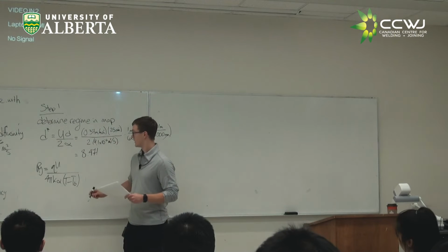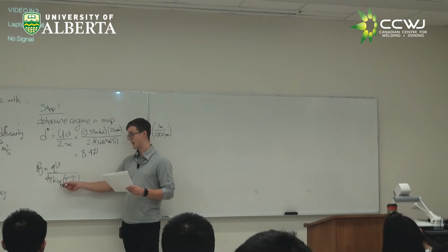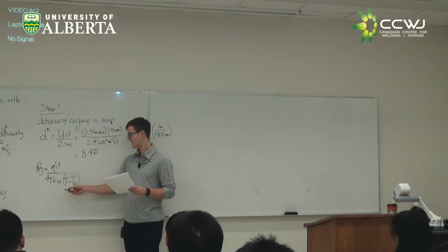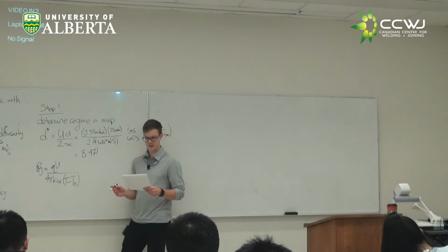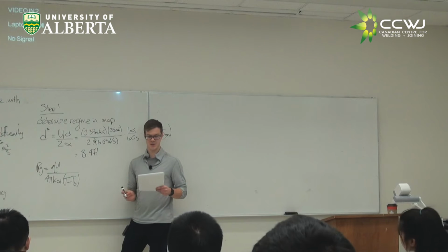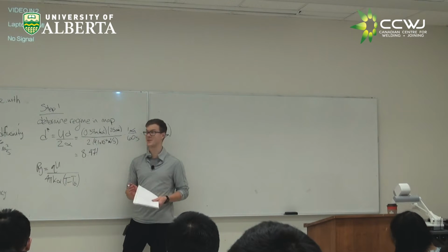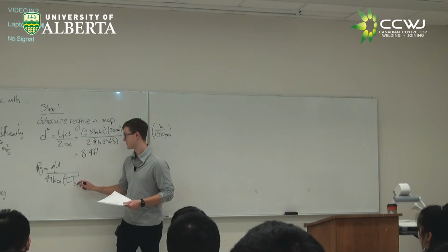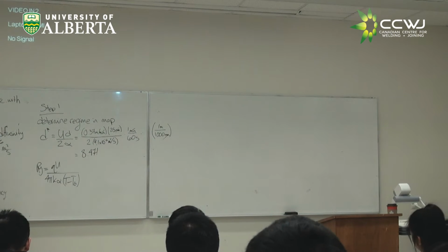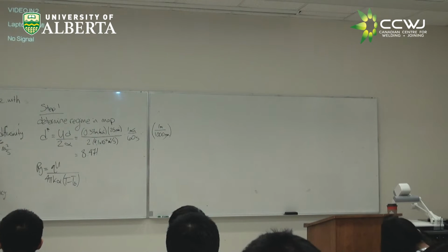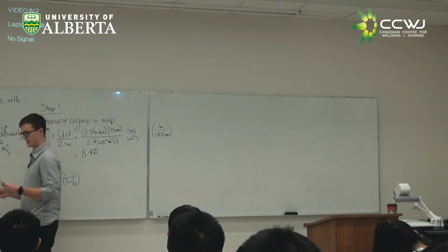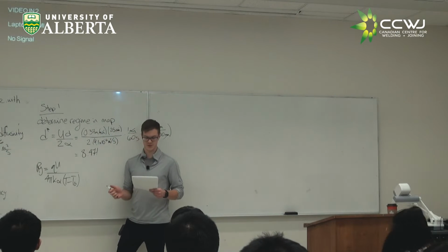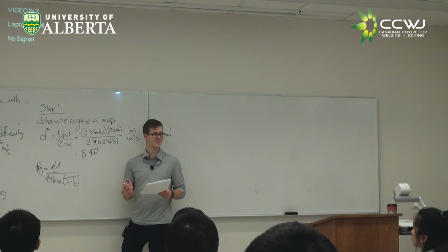So, Q we have, V we have, alpha we have, we're going to need K, and we're going to need T minus T naught. Now, in this case, we didn't give you any preheat temperature, so I think it's safe to assume there's no preheat. So we can say T naught is 20 degrees C. What about T? Anyone have a suggestion for the heat affected zone? 718?